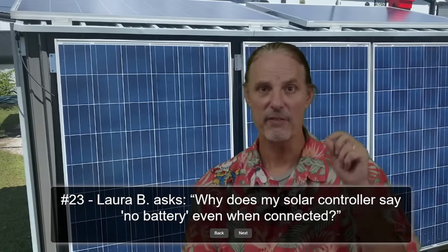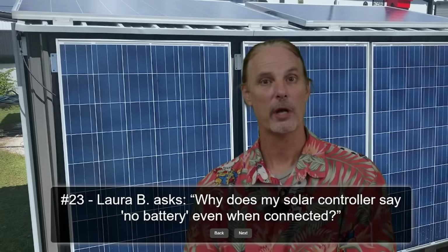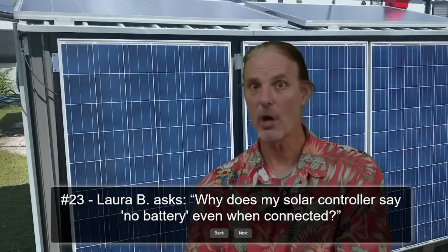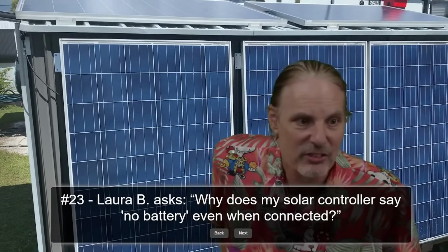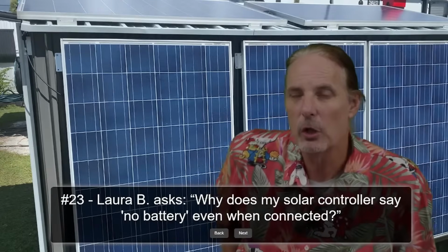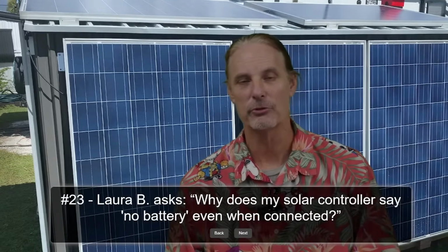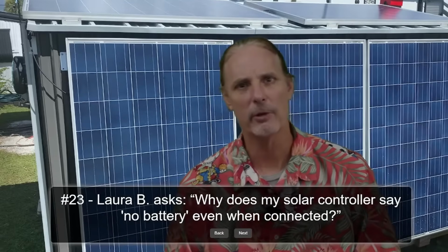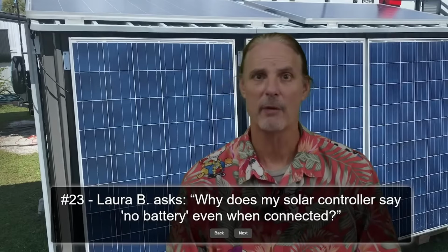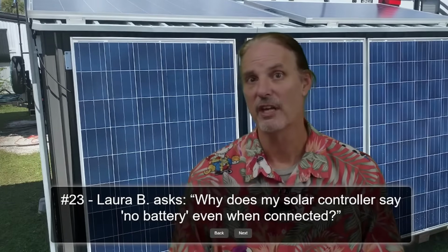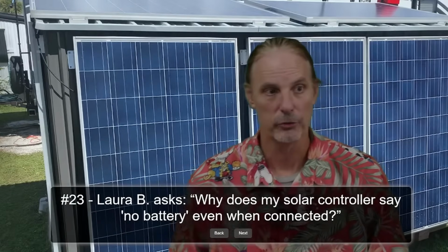In your case, if it was working and now it's not, my suspicion is you have a bad cable or a bad communication board in either a battery or in your inverter. But if the solar controller says no battery and you are running closed loop, then I would start with the cables and make sure that they're good. If the cables are good, then I would check to see if one battery would communicate, or if there's a particular battery causing the problem. If you only have one battery, then I would try setting it to lead acid and see if it does work without the battery configured in closed loop mode.